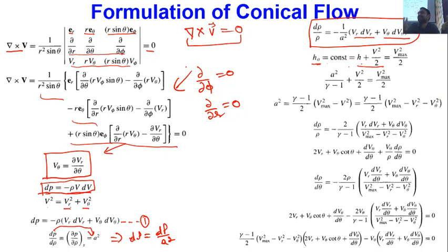I will be having the maximum enthalpy, maximum velocity. Okay, so if you are having, say, flow with some enthalpy and some velocity, now you are allowing it to expand such that its complete enthalpy becomes equal to 0. So all the enthalpy the flow is having is going to convert into velocity. Ultimately, whatever velocity we get is the maximum velocity we can achieve from a given flow situation. Is this point clear?